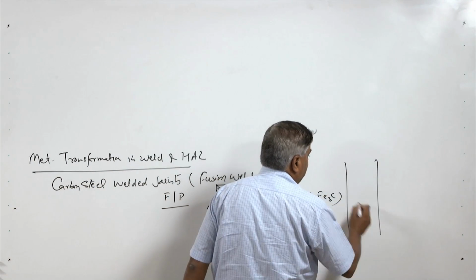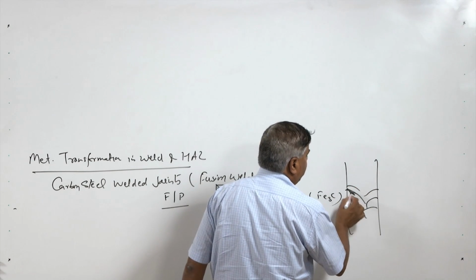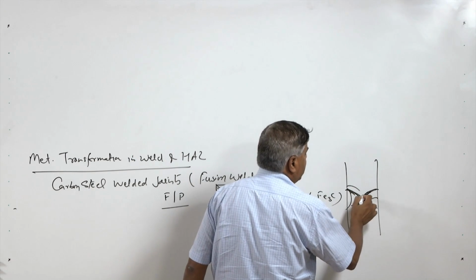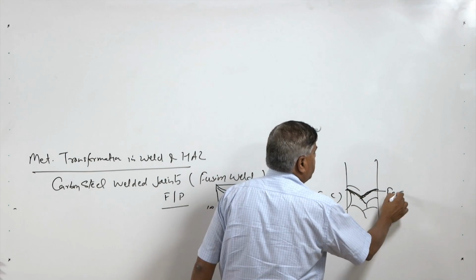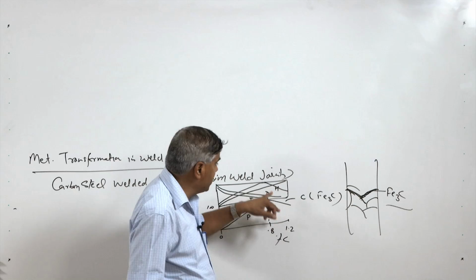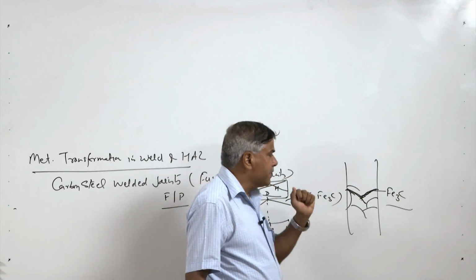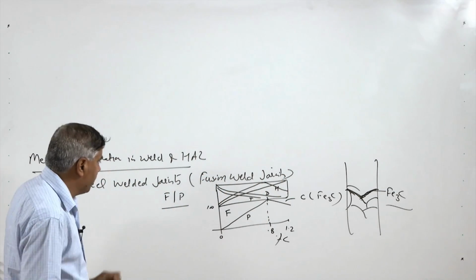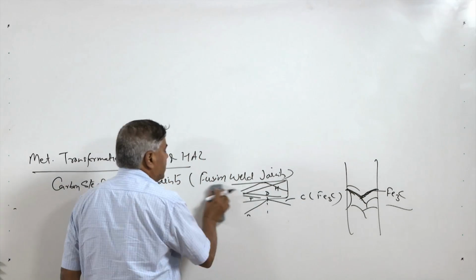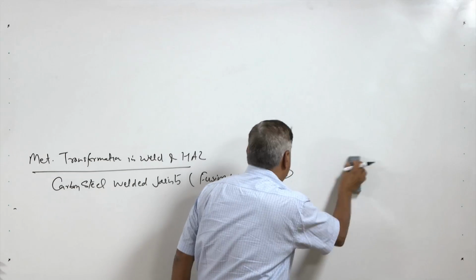So, being hard and brittle, say these are all the pearlite grains, and when the hard brittle phase starts appearing along the boundary, which is very weak in strength. When the Fe3C is in discrete form, the reduction in strength is not much, but the significant reduction in strength takes place when the continuous network of Fe3C is formed. So, basically with the change in carbon content, there is a significant change in the mechanical properties due to the changing proportion of the various phases which are being formed.